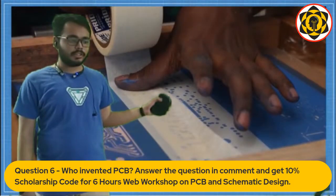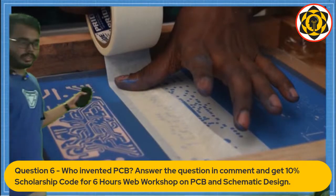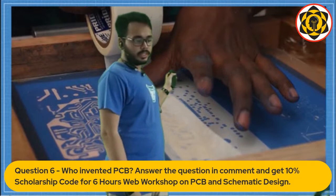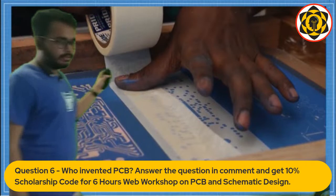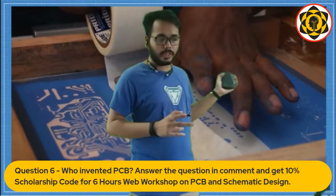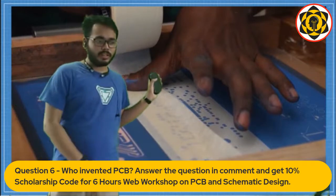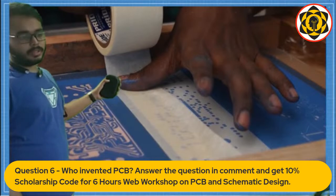Next is sealing of this part. As I showed you earlier, we have 3 different stages on the single screen, right? But we are not doing these 3 stages in a single frame. First we are doing this one, then this one, then this one on the same copper plate. If we just drop that paint on the surface, it will spread everywhere and destroy the whole screen. So to save the other parts, we are going to apply paper masking tape on the other parts of the side.